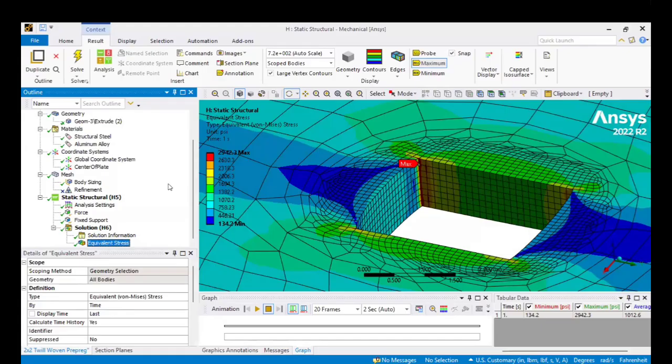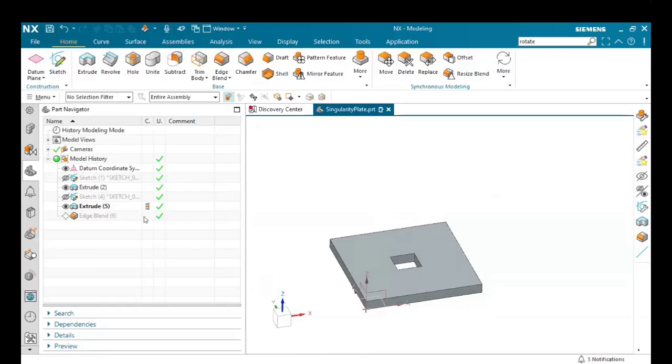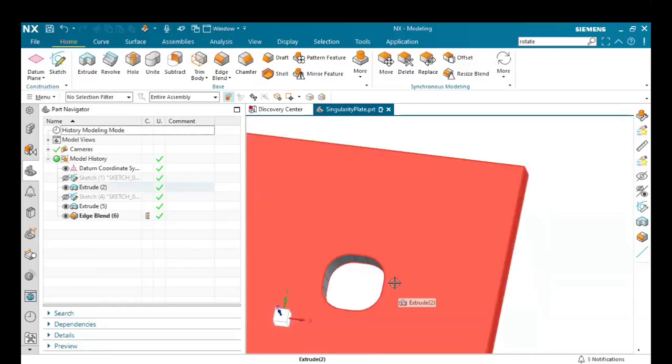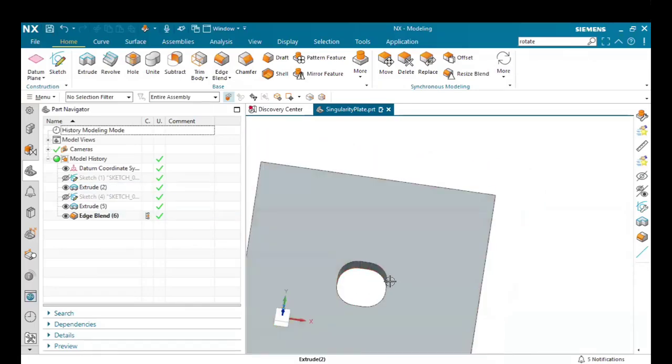So when I was covering the Comet failures that you saw early on with the square windows, the reason I had to move away from that is because they kept failing at the window because they were square. And so to accommodate and fix this issue, they had to go to elliptical windows, which is what you see today in airplanes. So a good design practice is to stay away from this kind of approach, right? Fillets are very helpful. It's to move to something like this with more of a fillet, right? You still have most of the functionality of the hull, but you remove the sharp corner.